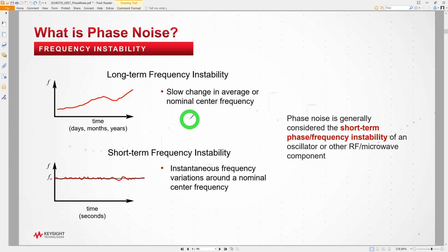Even for wireless transmitters, this can be pretty important. So if you have a crystal that ultimately sets the local oscillator of the wireless transmitter, that's the frequency you're going to be transmitting over the air. And if it drifts too much, you could even go outside of the range which you're allowed to transmit. There's a whole bunch of discussions around that, which we may do in a different video.